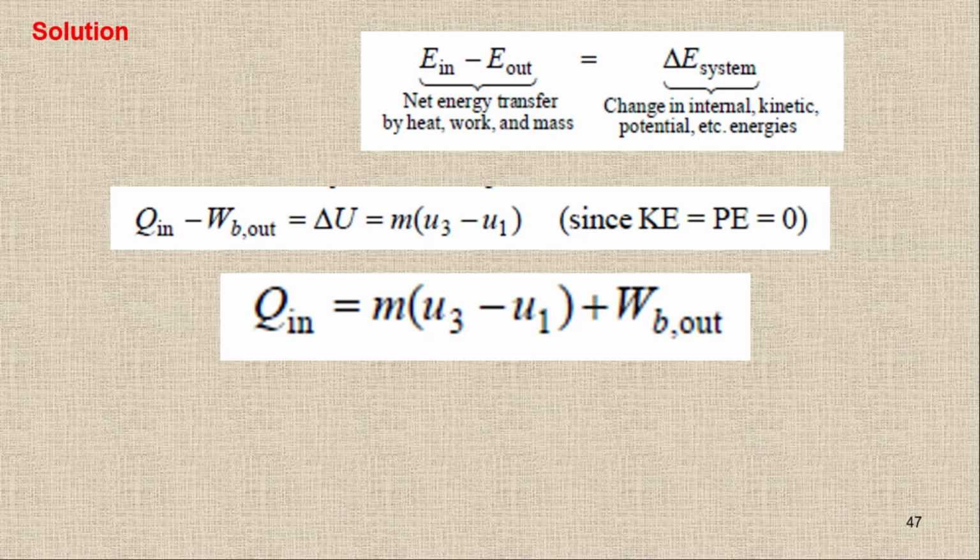So moving forward, this is the PV diagram. Here, you can see we have state 1, which is 250 kilopascal saturated vapor. Now heat is transferred and it is moving up at constant volume until the pressure is 300 kilopascal. After 300 kilopascal, the piston will move upside, and during the process 2 to 3, we have a constant pressure process.